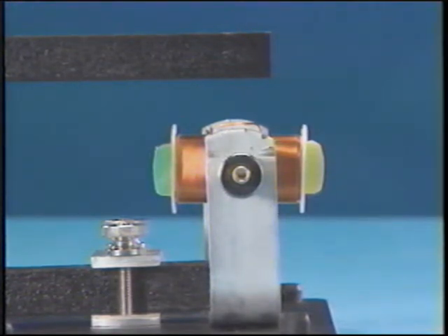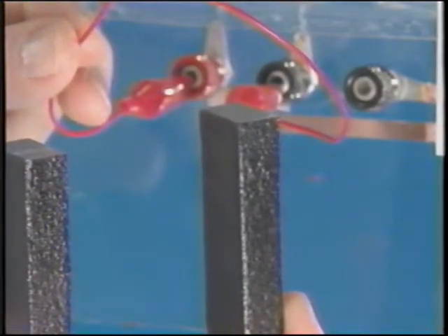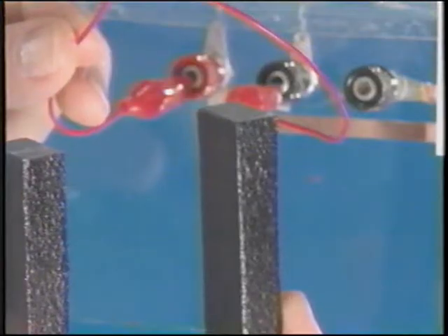It's important to realize that proceeding from this point in the rotation, the yellow end of the coil will now be cutting the magnetic field in the opposite direction. From an earlier demonstration, you'll remember that when the magnetic field was cut in the opposite direction, a voltage of an opposite polarity was induced. It's this principle of AC generation that creates its alternating aspect, where polarities are reversed.